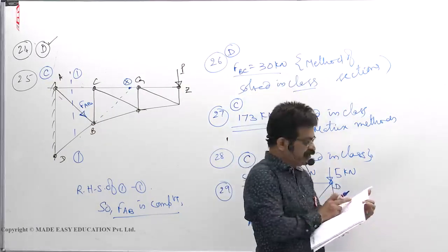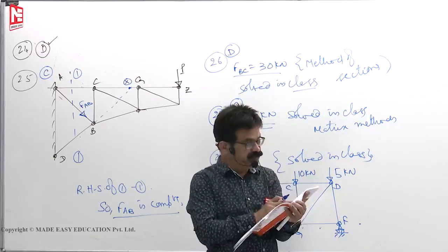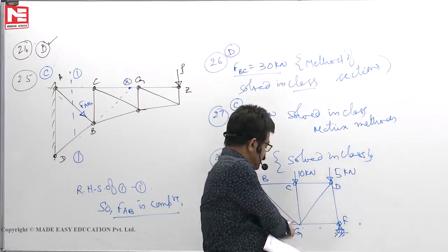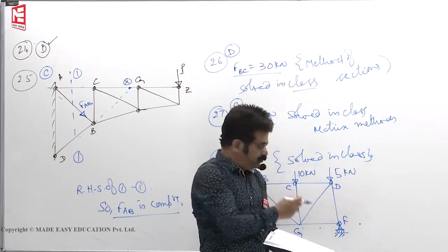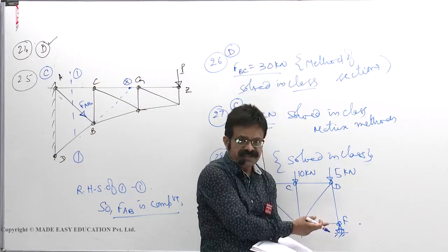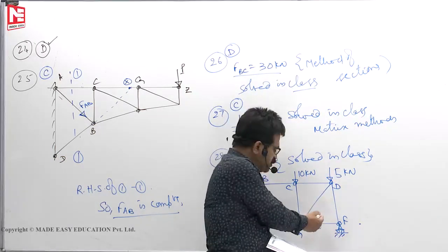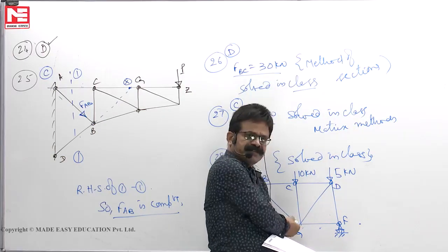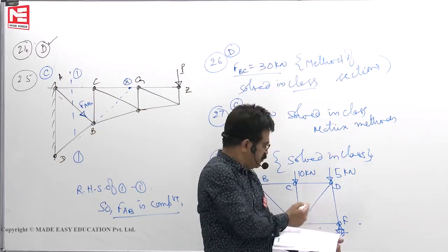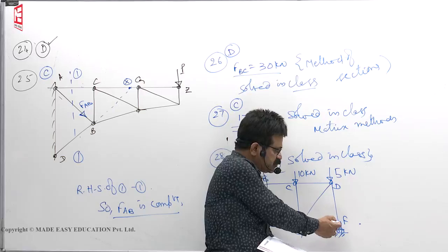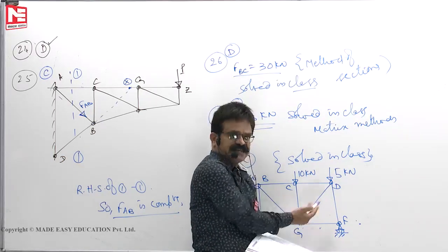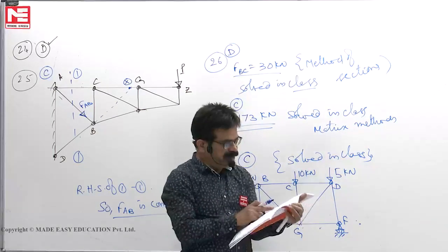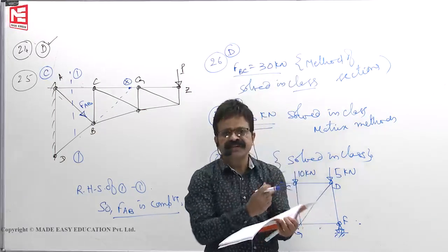Let us see the pin jointed truss shown in the figure. Two members they have given, you see. Only if they say AG, let us say. For this loading, GF member force is 0. Force is 0 means deformation is 0. This is 5 mm, say. 5 plus 0, 5. Otherwise, if they give the horizontal displacement as the deformation of AG, then that also is correct. But he has given minimum two members, then accordingly we have to select.